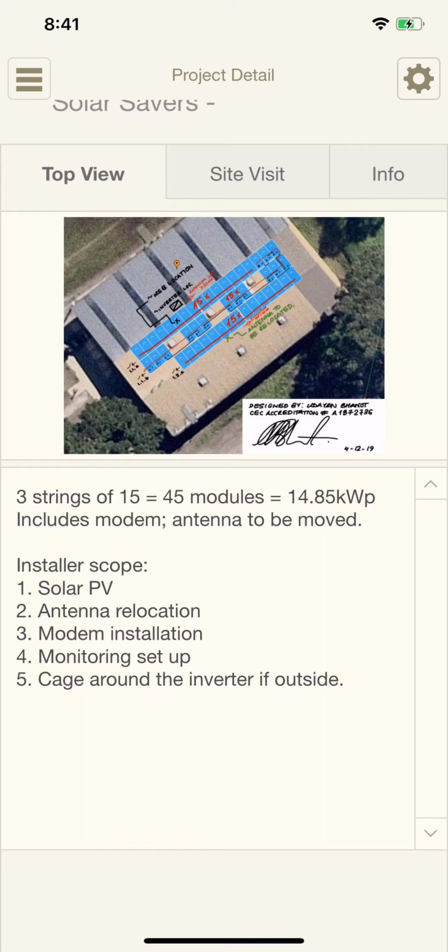In some very, very rare cases, the monitoring was not going to be set up, but of course, as you know, under AS5033 we have to provide earth fault monitoring, and that can either be done through the software or through an external alarm.